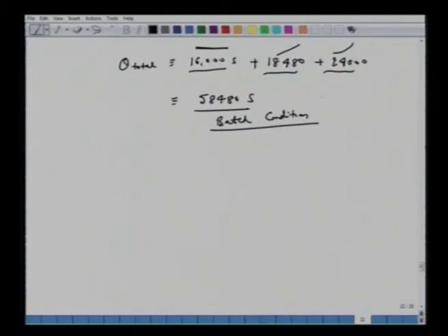So it's a very simple example, and here we have made use of certain analytical expressions, or certain numerical calculations, to calculate the last quantity. We also said, if you recall, that one very good approximation which can also work is to assume that from B to C, which is a constant rate, when you hit the critical moisture content, the rate decreases linearly. So we ignore this D point here, or at least we approximate that the rate which decreases non-linearly is very close to this. Very approximately we can say that it's linear throughout.